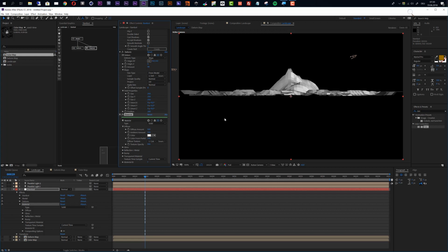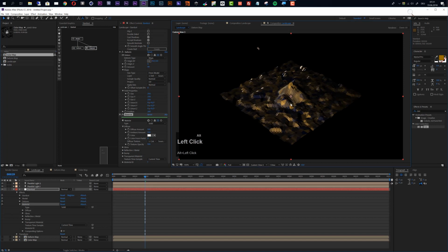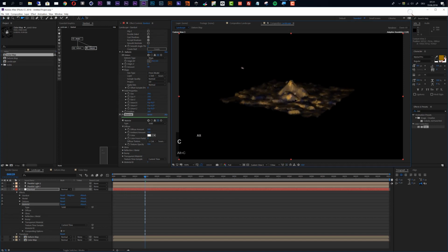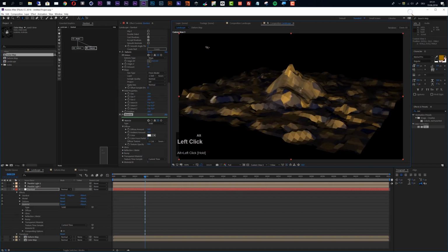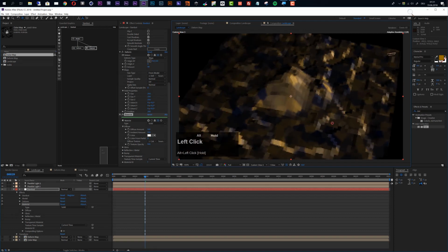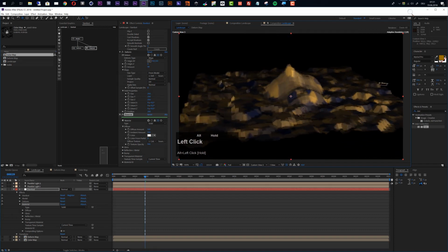And you see that nothing is happening, and this is because the color from particle value is set to 100. And if you reduce this to 0, then our texture will be colorized. If this is set to 100, then the material is looking for a particle node and the color of this particle node, but we have no particle node, so we have to reduce the color from particle to 0, so that our diffuse texture is working. And now you see that we have a nice coloring of our landscape. Okay, so far so good.